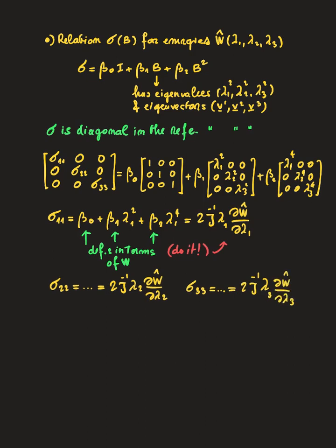You may say this was much more simple, but in fact to get here we in any case have to pass from the invariants, and don't forget this was important to get all the structure leading to the Piola-Kirchhoff stress, to the nominal stress tensor S, and then from there we understand how the Cauchy stress is done. You see, it's all a work in progress that led us here. Okay, I think with this I will just conclude this lecture. It was, I have to say, probably not immediately easy. I don't think there is any intrinsic complexity in what we have done.